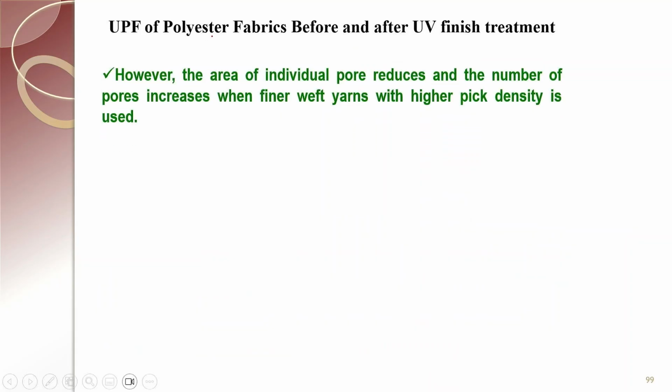So, regarding the UPF of polyester fabric before and after treatment, the area of individual pores reduces and the number of pores increases when the finer weft was used with higher pick density. We wanted to keep the total pore area constant, that is, to keep the cover percent constant.